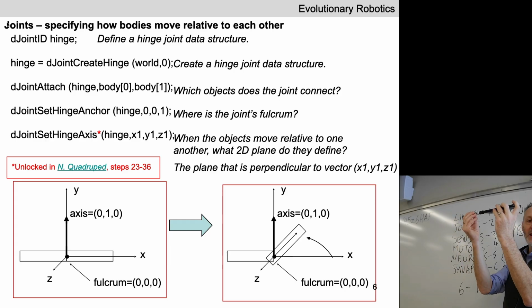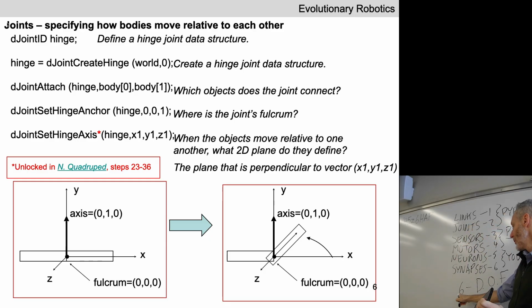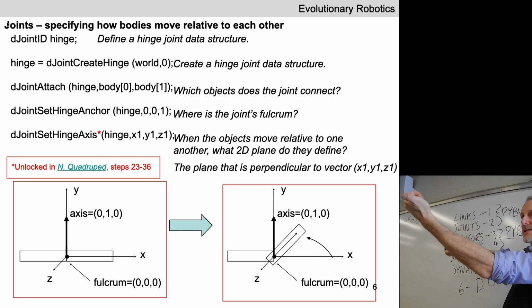The moment we connect two links together with a joint, that joint is going to remove one or more of the degrees of freedom of the links that are attached together. These two links are no longer free to move along any of its 6 degrees of freedom. Okay, let's see how. Let's have a look at my elbow joint. Luckily, my elbow joint constrains my lower arm from moving away from my upper arm. That's kind of the whole point of the elbow joint. Yeah? Okay. So let's assume that this is the Z.